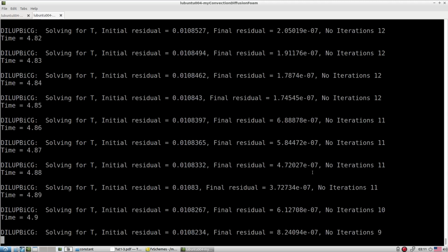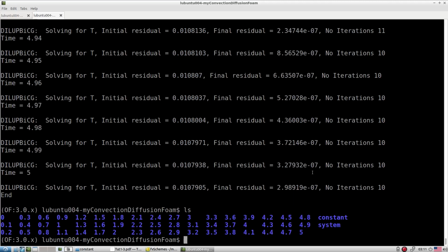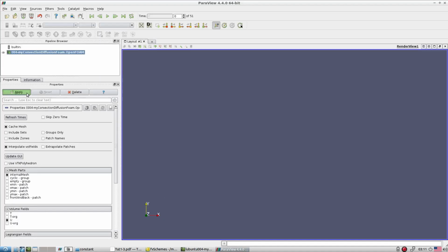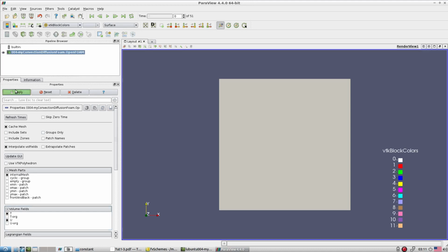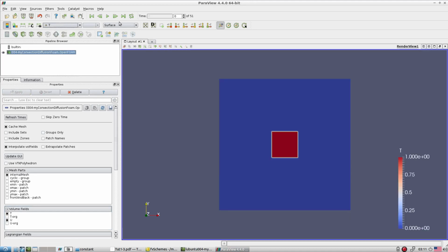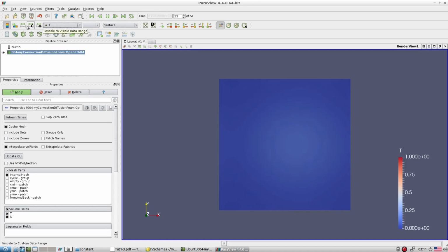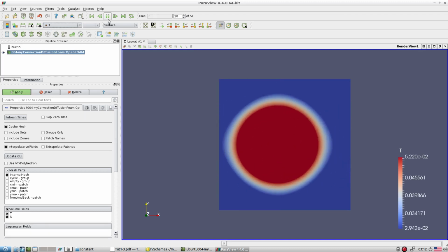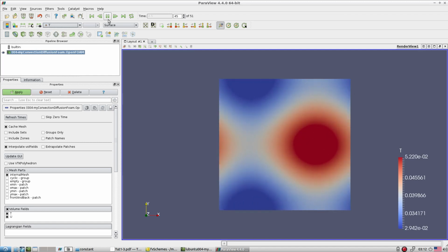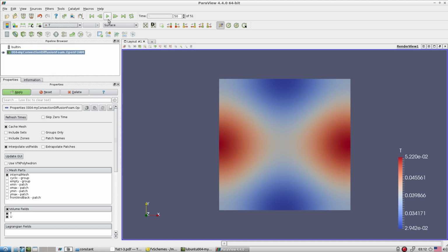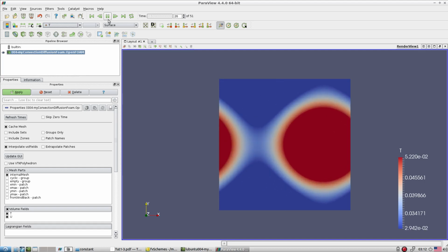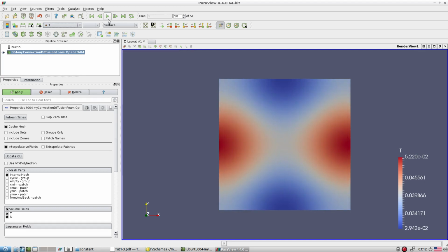So we run for 5 seconds. Now check how exactly the scalar transport of that quantity is appearing. So here is the T. It's almost diffused, because of the diffusion characteristic, and it is a periodic flow. Look how it diffuses, you can see very quickly. So that concentration T is propagating inside the domain, and it's diffusing in nature.